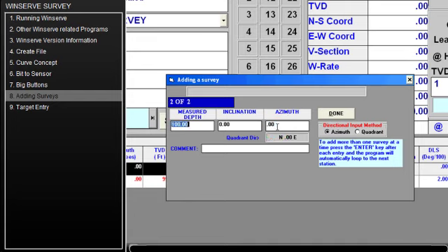We'll come down here to 200 feet and we'll start giving ourselves a little bit of play here and get some directions and whatnot. And 300 feet, 0.4, and say 12, and 400 feet, we'll say we've got 0.6 degrees, and we've got 34 degrees azimuth, and 500 feet, we'll say that we're back down to a 0.4, and we have 49 degrees.